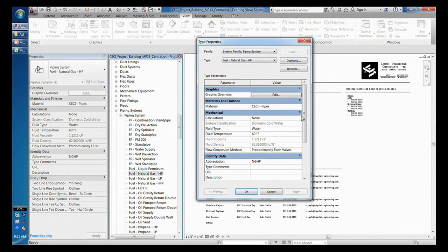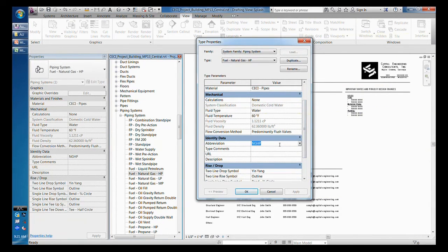All right, picking it up here, and I'm of course using the system abbreviation for my filters to know which system pipe to turn on and off. For this in the past, I had to create unique pipe types, which I was totally against, but it was one of those things that I wished it was working better, and now it is.